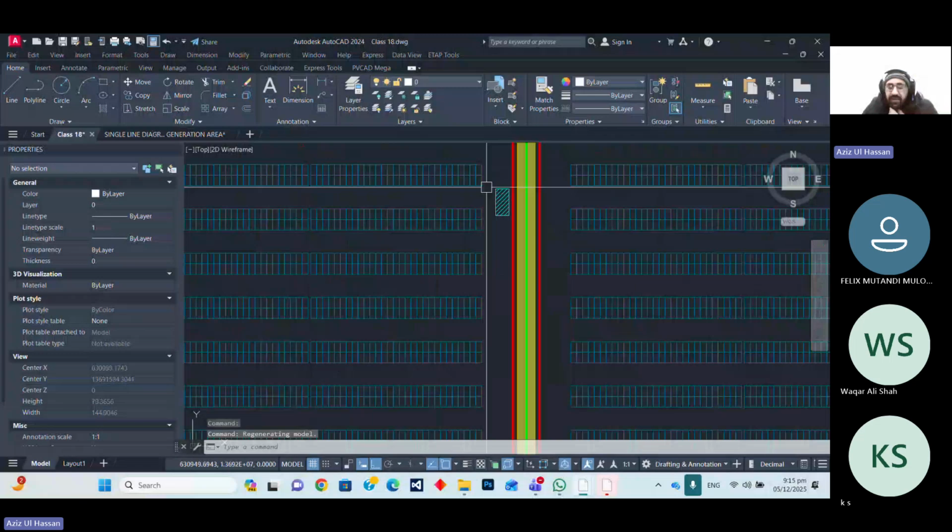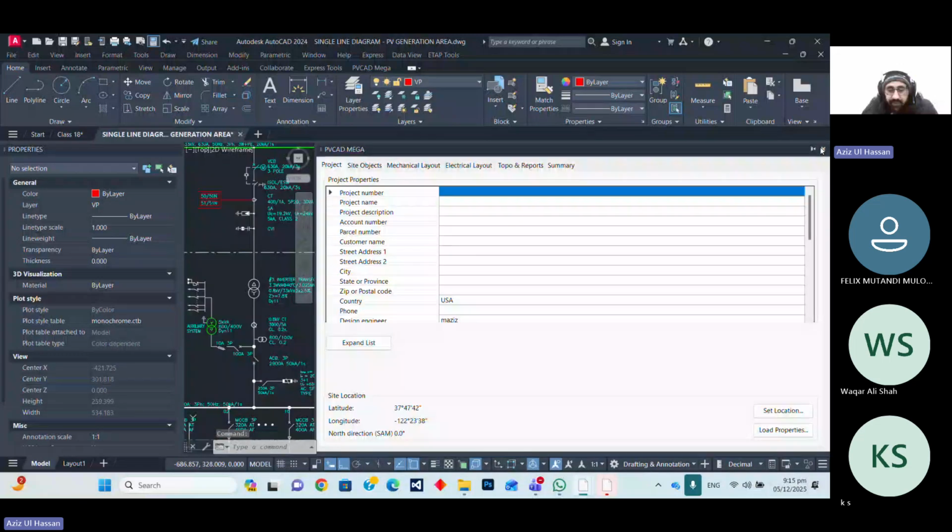The total DC capacity connected to that is 3.5 megawatt. We have connected directly to the MPPT of that inverter, and then we have combined these MV stations to that switchgear. So basically it is the overall picture which I'm just showing there. This is basically the container solution.